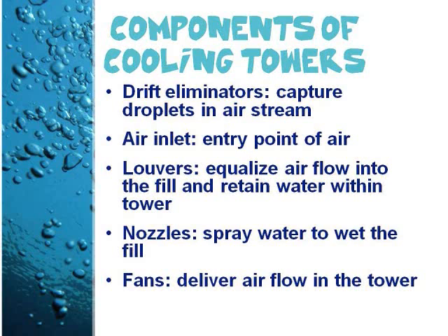The air inlet is the point of entry of the air entering the tower. The inlet may take up an entire side of the tower for the cross-flow design or be located on the side of the bottom of the tower for the counterflow design.